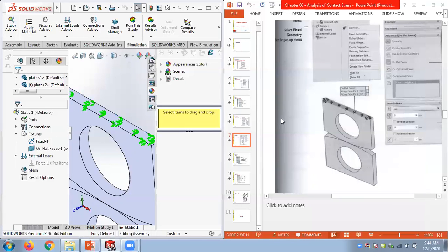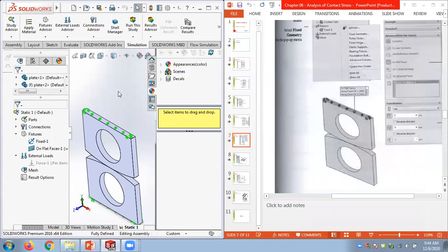So press OK. What I have given here is, now I have applied a load, I have fixed the bottom, I have given some motion restraints here. In y direction only there will be freedom, x and z direction we restricted, and we can give external load.